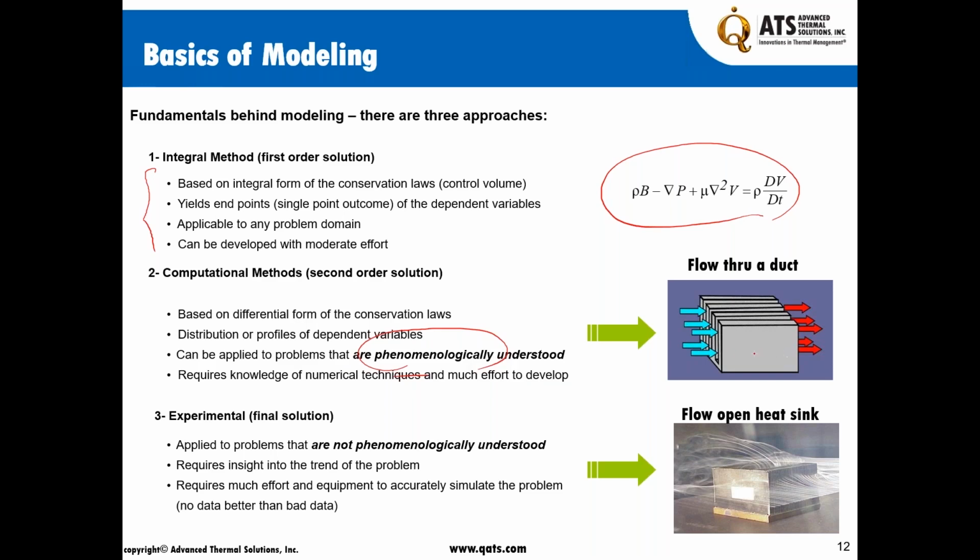When I look at it, for instance, flow through a heat sink, that the top is covered like this, and it's a ducted flow. It's a very, very defined problem. And the models would work very effectively, even for some of the problems that are open channel. A lot of work has been done on the heatsink, for instance, that we can address the open channel, like the picture that you see in the bottom. But we have to remember that the mathematical models that are deployed in the computational tools, they're very defined, and we need to make sure that it is applicable to the problem that we solve.